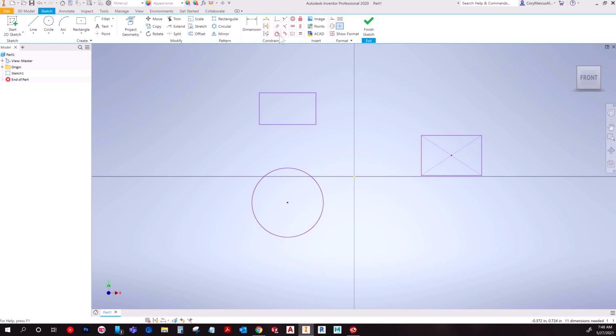So just to show how controlling these are, I can hit this tangent and put it on there, and it actually pulls the entire sketch piece all the way over there. And before I dive in too deep, the best way to tell if something is fully constrained is to click and hold and pull. And then as you can see, it moves, which means it's not fully constrained.